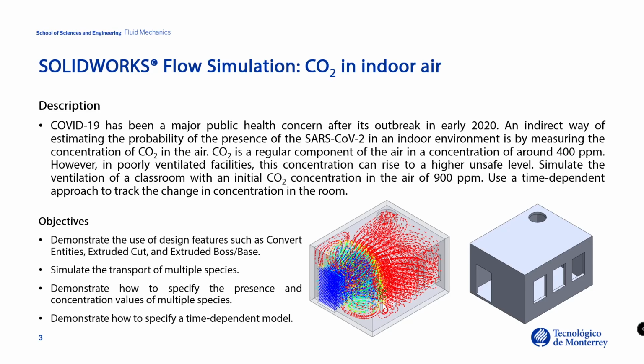In this case we want to demonstrate how to use some design features, for example, convert entities, extruded boss and extruded cut. And we want to simulate the transfer of multiple species. We also want to demonstrate how to specify the presence and the concentration values of multiple species, and finally to demonstrate how to specify a time-dependent model.